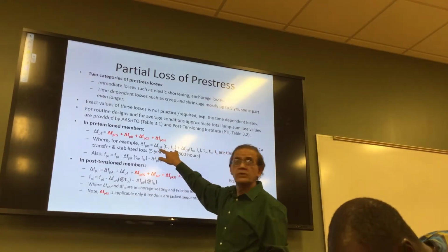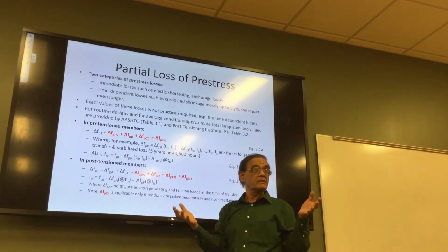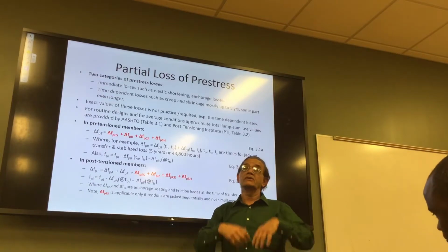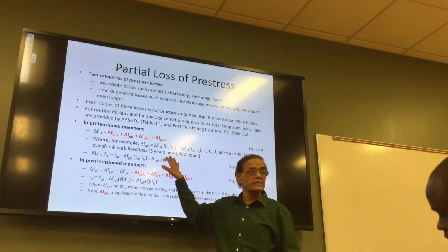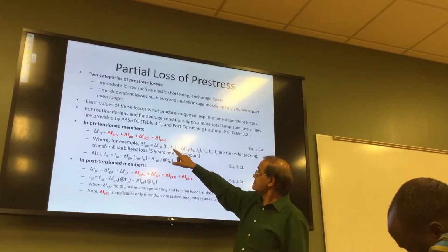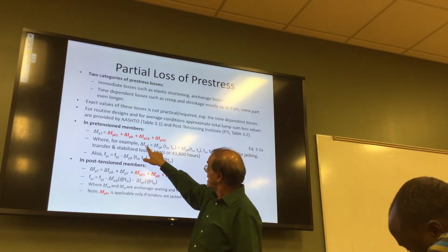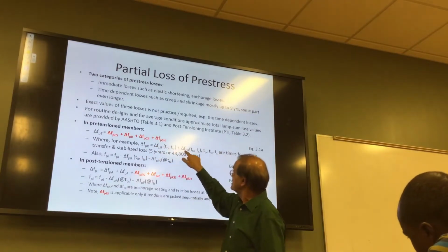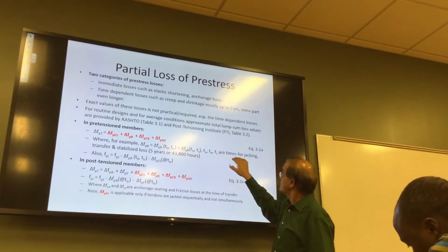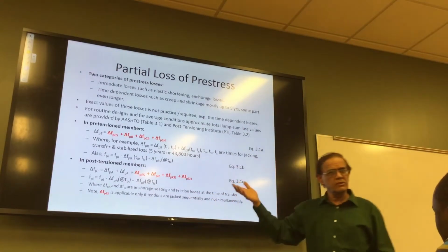Right? So for those few days, you calculate. T0 is 0, obviously, because that's when you stretched it. Then you left it there for a day, then you came and cast the concrete for another 6 hours, and then you waited for next day morning. So that could be 2-3 days here. But those 2-3 days between T0, which is practically 0, to TR, so you put that in. So the relaxation is from there to there plus relaxation from TR to TS, where T0 is 0, jacking, transfer, and stabilized loss, which is 5 years or more, right?